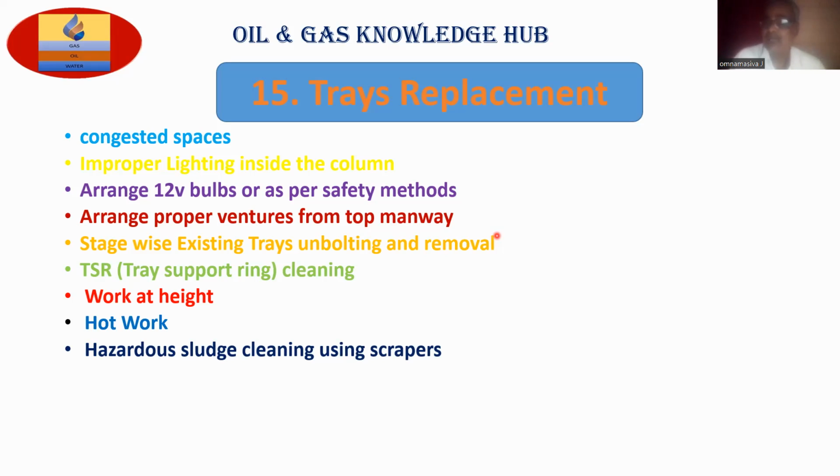We have discussed pyrophoric material in my previous videos. If you want to work in shutdowns and turnarounds in the oil and gas field, you should know the terminology. Pyrophoric material means once it is open to the atmosphere, to oxygen, it will catch fire. That's the reason I explained in previous videos how to store pyrophoric material. Try to learn, try to understand and work safely.